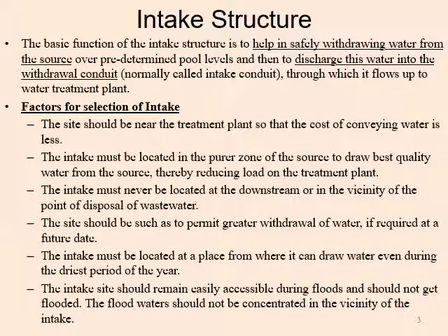The intake must be located at a place from where it can draw the water even during the driest period. So in a river or in a lake or any canal or stream or even in a reservoir, the water quantity should be available throughout the year and for all seasons, including the driest period where we will generally get less amount of water in the source.